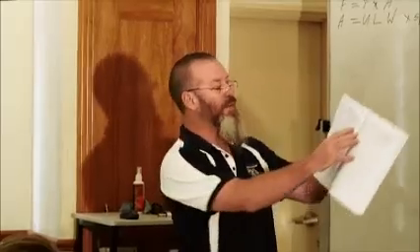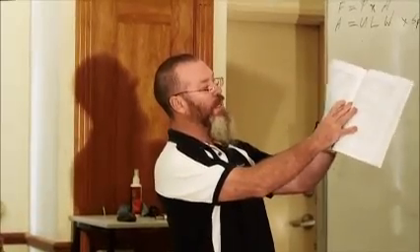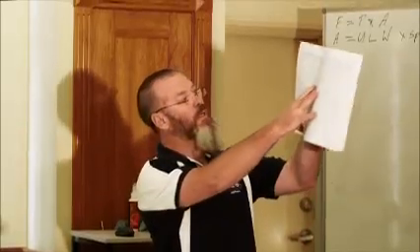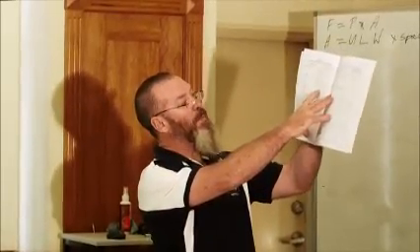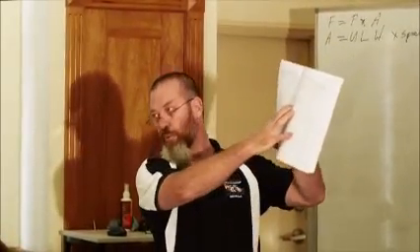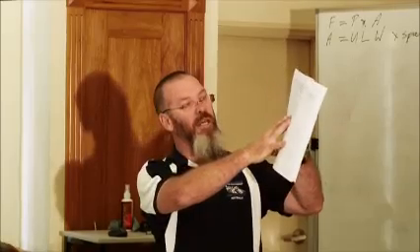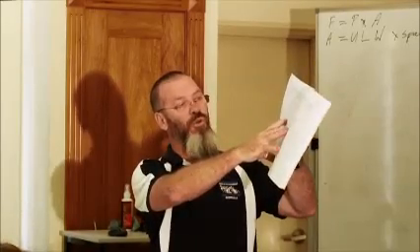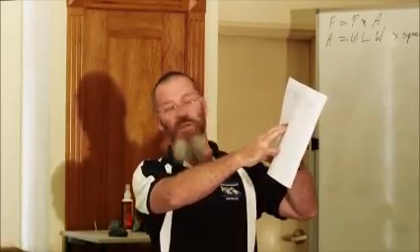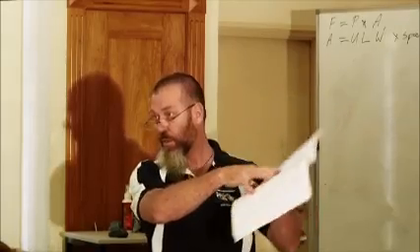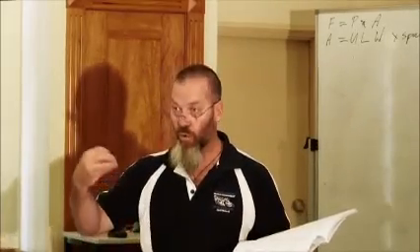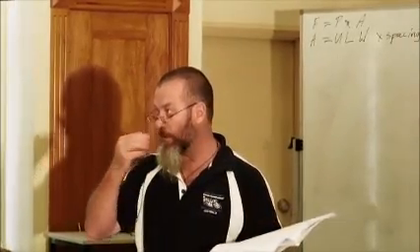So you start at JD5, and we've calculated 0.29 of a kilonewton. So I start there and I go, one plain shank nail won't do it, 0.21. So you go to the next one, and you'll see two 3.05 nails will give you a resistance of 0.42. So that's equal to or greater than that 0.29, isn't it?